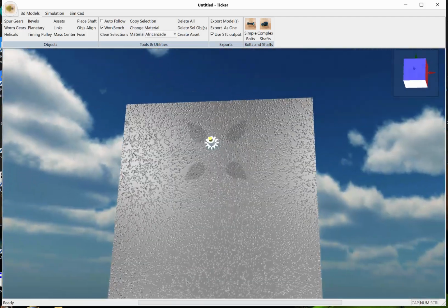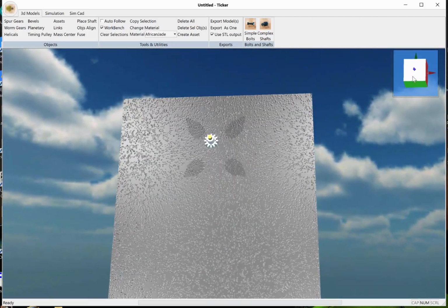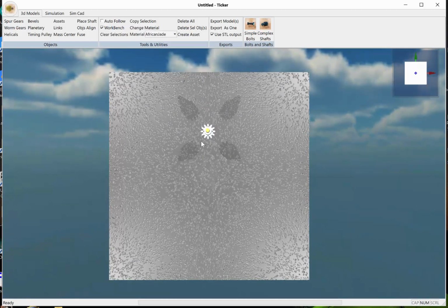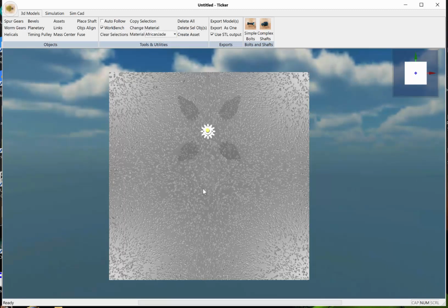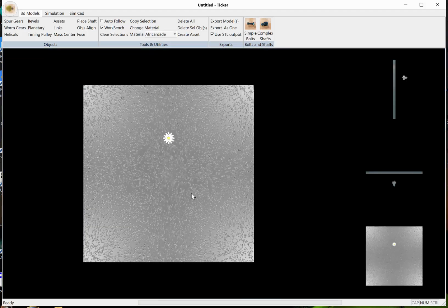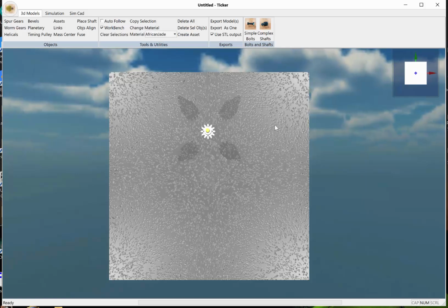Now, before I go to the CAD drawing, I'm going to make sure that I hit the plane, because I want to look straight in at this gear so that I don't have a perspective problem on my drawing screen. Incidentally, there is a keystroke button, the Alt key. If you press the Alt key, you will go to a temporary ortho display. It'll show you a straight-in display of your mechanism with no perspective distortion. And you'll get 3 displays on the side to show how it looks from the left, right, and top and center.